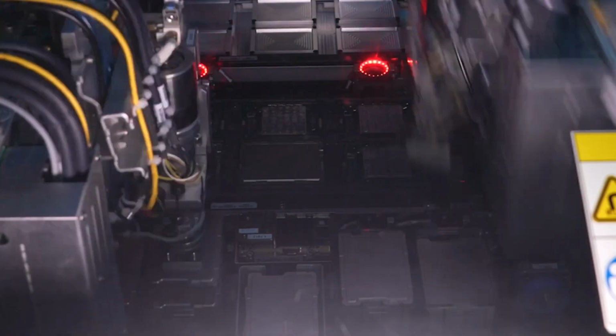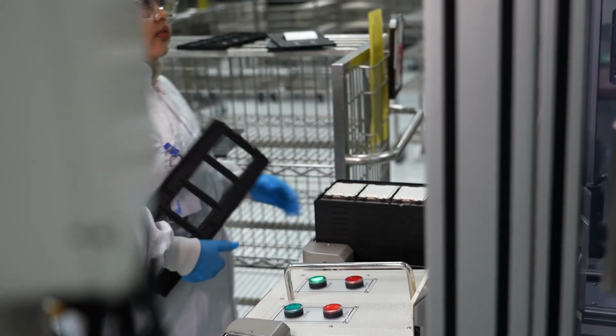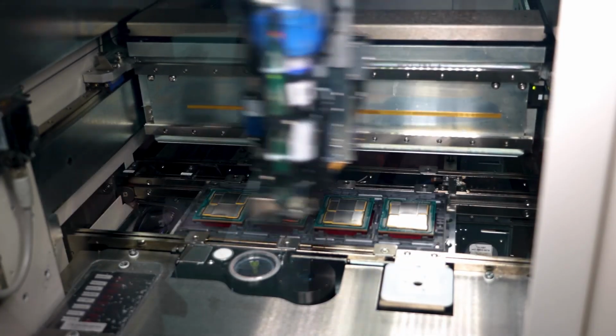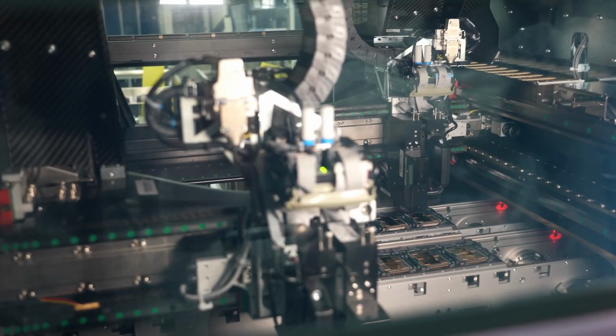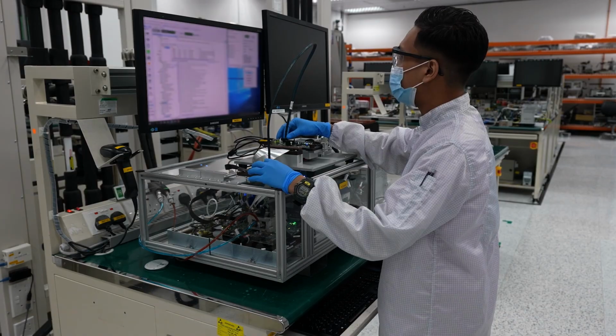After that, circling back to that singulated die test, we do have the option to test them again. Since we are able to test at the die level, we are able to test at the die stack level. And I think this is a big advantage. Sometimes there is a cost for adding a test step, so we have to use it judiciously. On Meteor Lake, we've been using it through development and sampling to make sure we have a healthy process. And then we'll evaluate how we use it in HVM, or high volume manufacturing, but it's still good as a quality monitor, making sure that the line is running well before we send the die to package assembly.